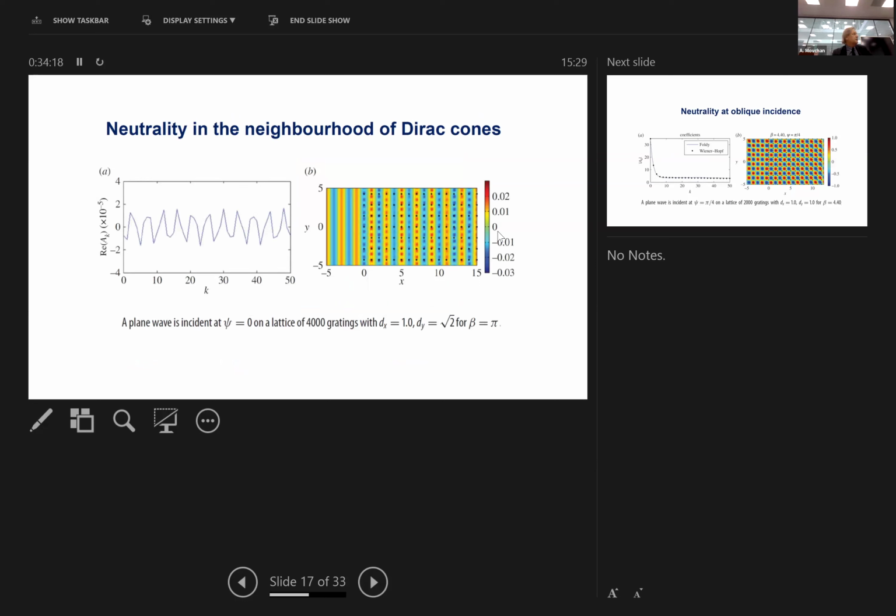So this is another example, and here you can say, how is it possible? Think of sending a wave with the nodal points exactly at the points where the pins are. So in a sense, nodal points are the points where the displacements are zero. Therefore, these pins are unperturbed. They don't produce any force. They don't produce any scattering. It's a very simple argument. But here you get it as a result of the analytical model. So that's the message.